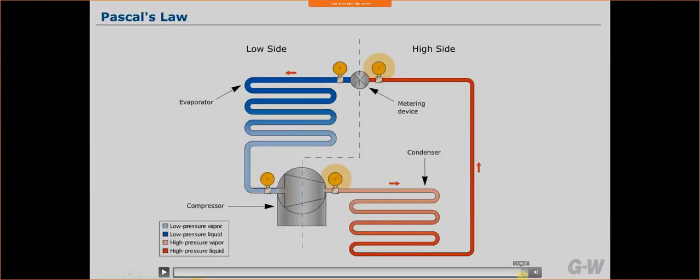So that's getting into the basics of refrigeration. We've got the high side and low side. We'll definitely cover that in more detail, but just to give you a basic illustration of how everything works: we've got refrigerant flowing in this direction, indicated by the arrows. We've got a cold refrigerant. Over here, it absorbs heat and comes to the compressor. The compressor is going to change the pressure.